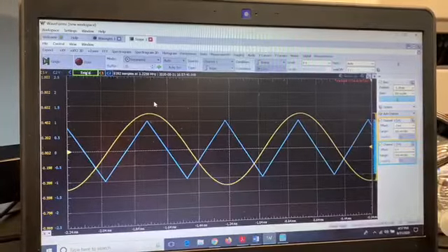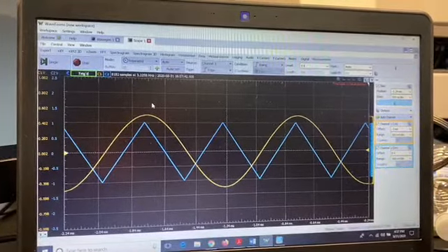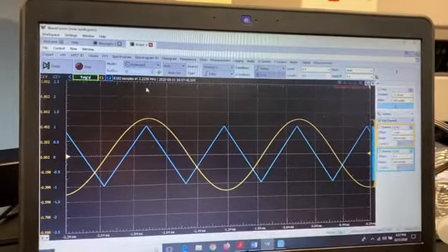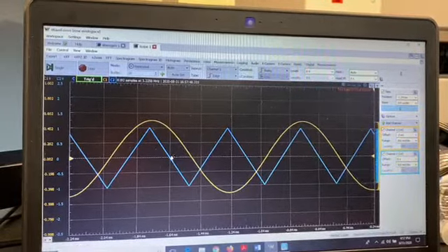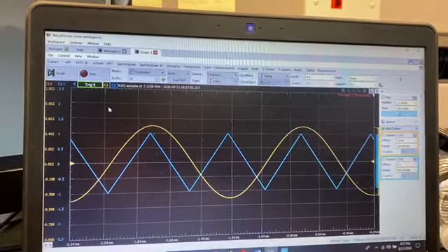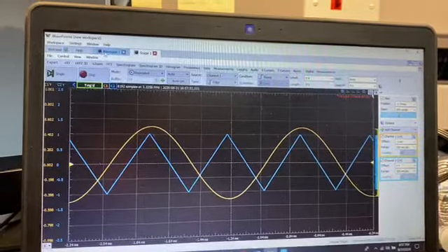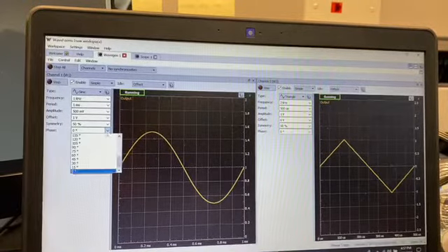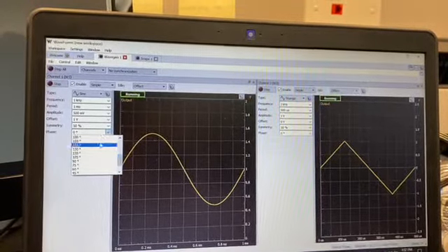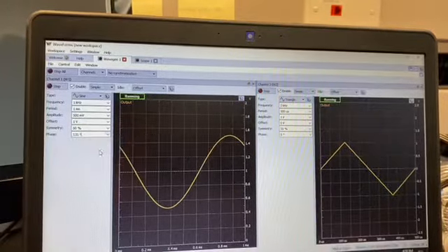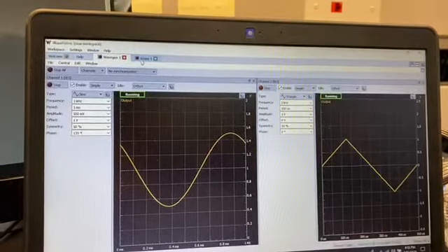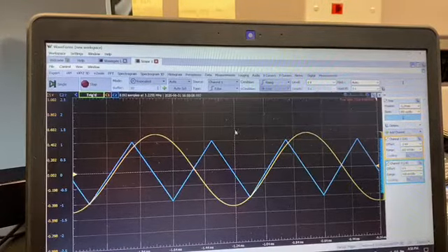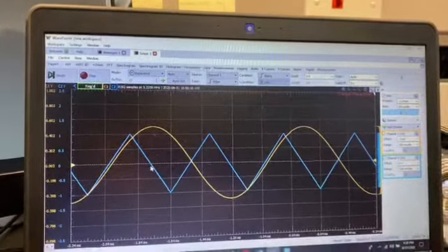In order to generate the XY plot of these two signals and get the sample result in the experiment, we have to change the phase between these two signals. So we go to the wave and we change the phase to 135, and then go to the scope, and here is the resulting signal with 135-degree phase shift.